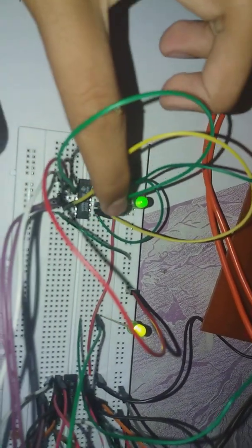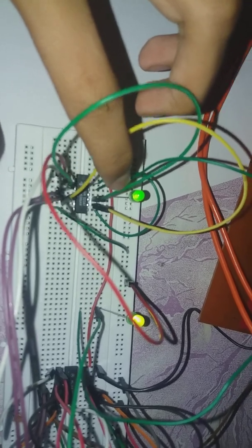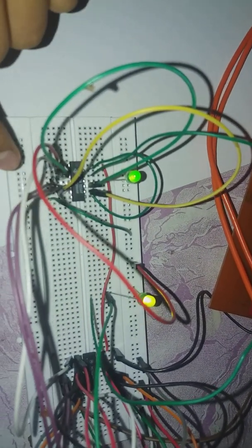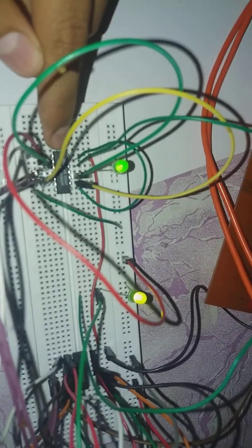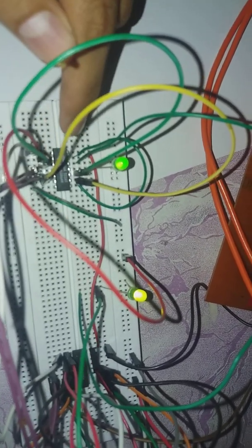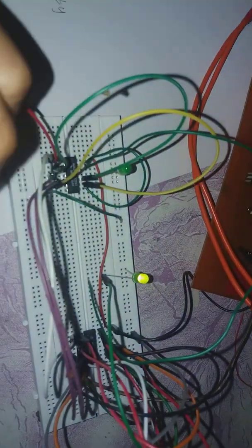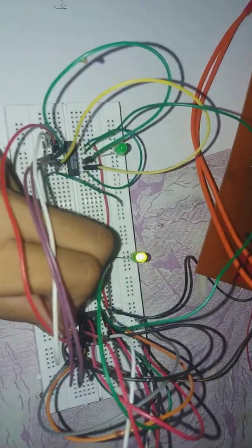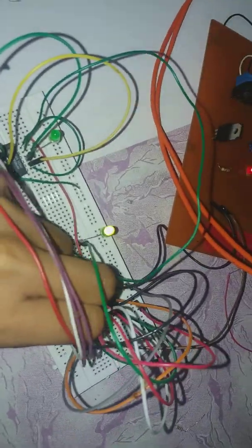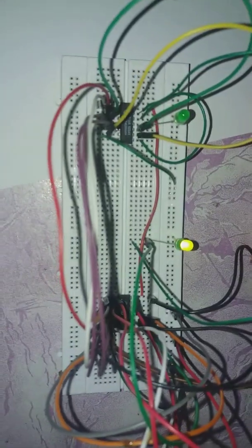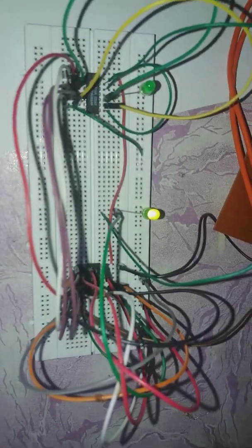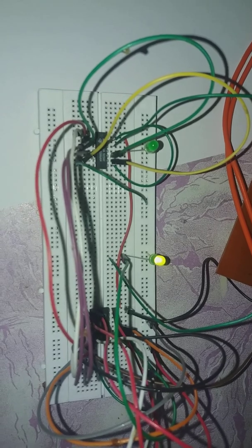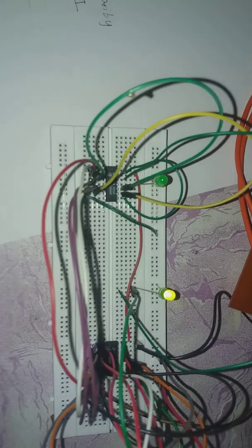See, this LED is now glowing, indicating that there is an error in the transmitted bits. So this is working fine. Now as soon as I switch it back to the same old code that was transmitted, it will stop glowing. As you can see, it has stopped glowing. Therefore it proves that this circuit is working fine and has the capability to check and generate a parity bit for 4 input even bits. Thank you.